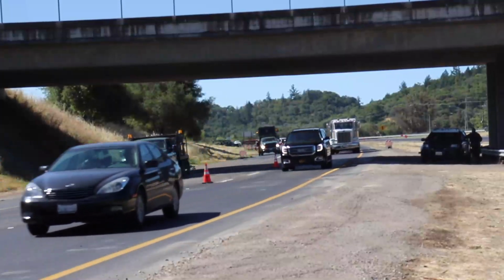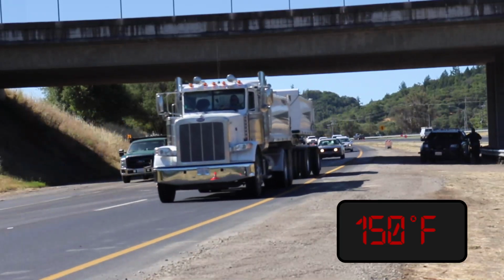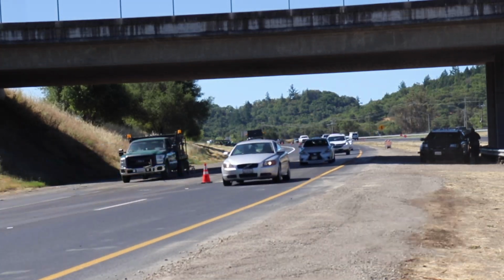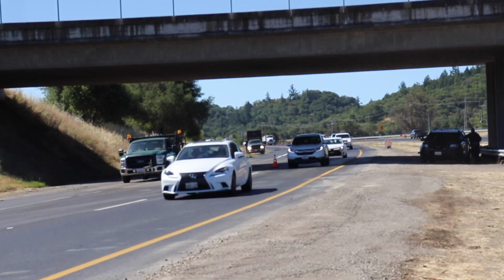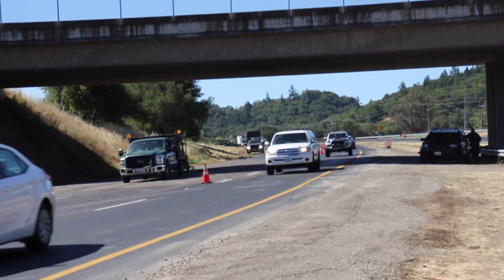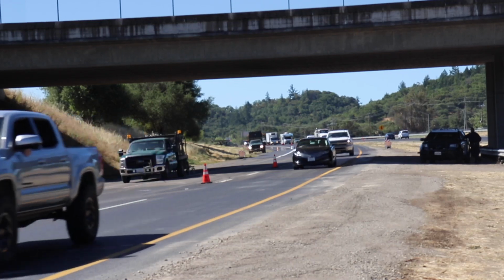Traffic should not be allowed on the finished mat until the surface temperature of the mat is below 150 degrees Fahrenheit. If this is not possible, a sand or dust blotting application should be applied at an application rate of 2 pounds per square yard. This acts as a bond breaker and not a cooling agent, and shall be applied only after all compaction effort